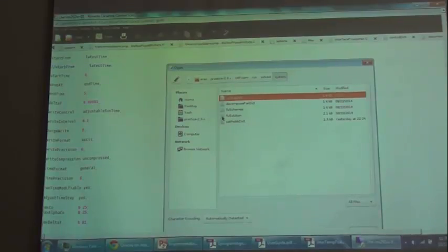What do you specify as adjustable? It's here. When you say adjust time step, that's the starting time step, delta t. So this is the starting time step that I have mentioned, and it's similar to what you do in Fluent. When you want to go for an adaptable time step, you can specify the maximum Courant number, and you can also specify the maximum time step that you can have.